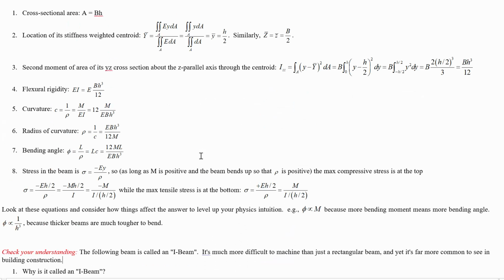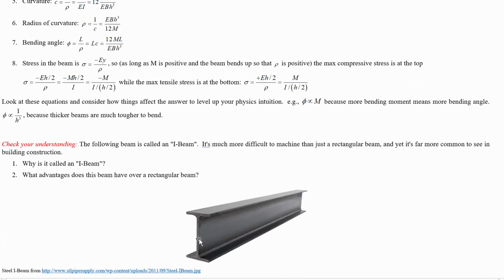Because this calculation of the second moment of area cares about the square of the distance away that a little piece is from the bending axis. So this is designed to maximize the amount of area at a faraway point from the bending axis. This beam does way more resistance to bending than if the same area were just in a rectangle, right?